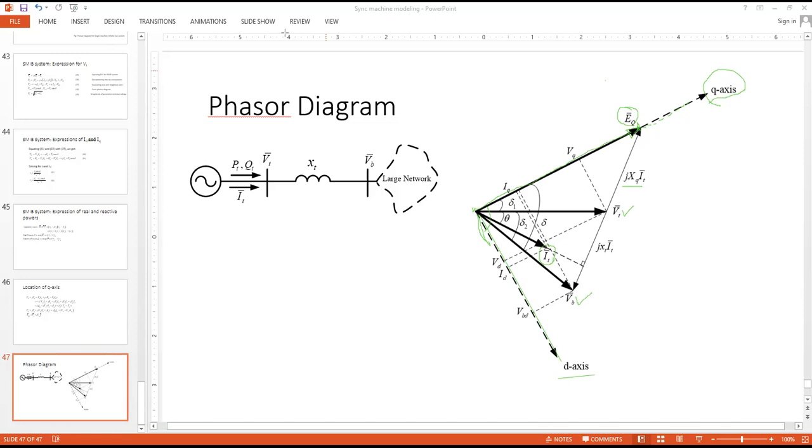Now we define our power angle or torque angle or rotor angle, whatever you say, that is measured from the reference. Okay, so the power angle or the rotor angle is measured from a reference, and now we say, well, this is our original reference for the whole system. VB is the reference. Although for VT we assume that it is lying along 0 degree, in that case VB will be some negative angle. For this diagram, it is VB minus delta 2. It doesn't matter, but this is the actual reference.